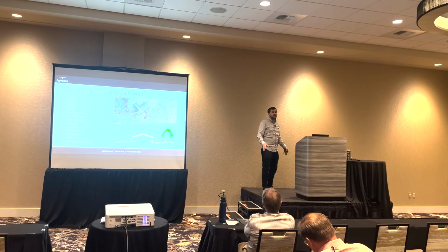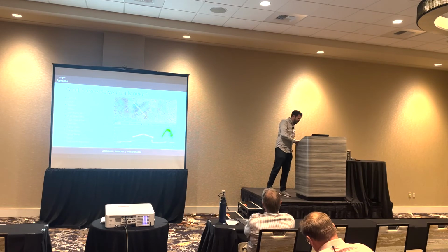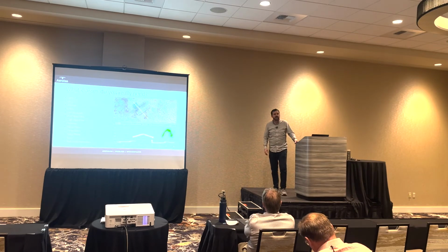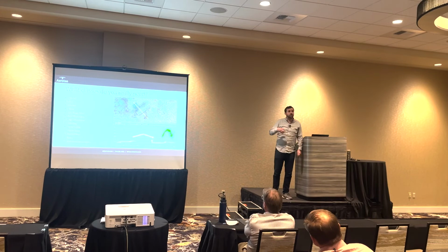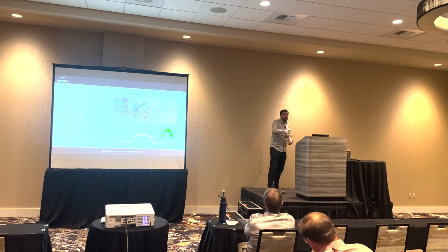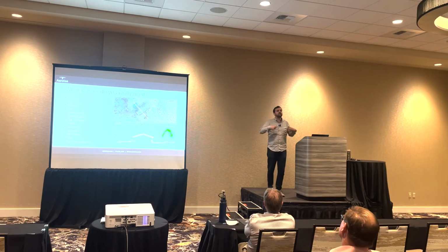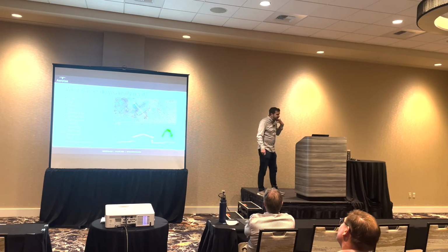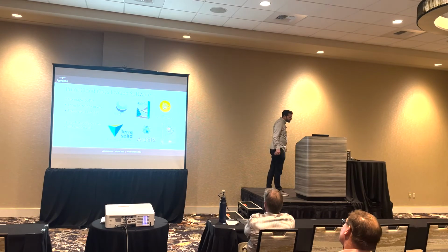Sometimes we do need edges of roads. If you're giving it to a power transmission company and they need to put it in PLS CAD, you need a ton of different classifications. But if you don't need more than ground and not ground, then it's a waste of time and money to start classifying everything else. It's another one of those questions. If you start thinking about the workflow at the beginning, you start thinking about what you need and then only get what you need, that's how you're going to save a ton of time.